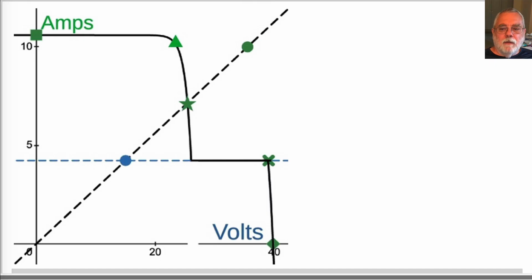Where do you think the microinverter or DC power optimizer will operate in this case? Near the X? Near the triangle? Can you work out all the voltages? Is the bypass diode on or off? Is the partially shaded solar cell sourcing power or dissipating power, and about how much? If this interests you, pause the video and work out this case.